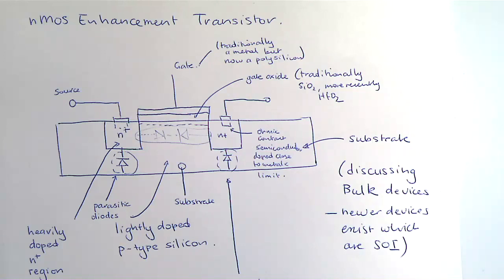And then, because you've caused a lot of damage to this crystal, you reheat the crystal in order to do annealing, and to actually activate these dopants. So essentially you're doing this at the nanoscale, because remember we said that this little 6 by 6 millimeter part of the wafer has billions of transistors on it.